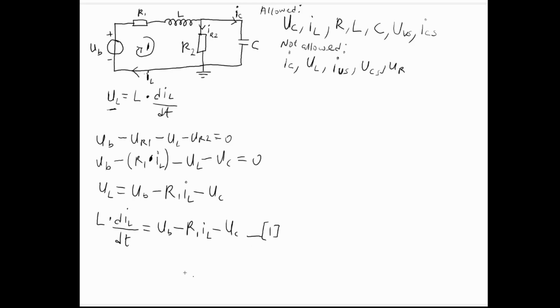So the second one is for the capacitor. Now we can write it out here. The current across a capacitor is equal to the capacitance multiplied by the time derivative of the voltage across it. All right, now, again, we look at this equation. We need the right-hand side in the final equation, but we don't need the left-hand side in the final equation. So what do we do? We try to derive or formulate a structural equation that would eventually eliminate the left-hand side, I subscript C, that's the current of the capacitor.